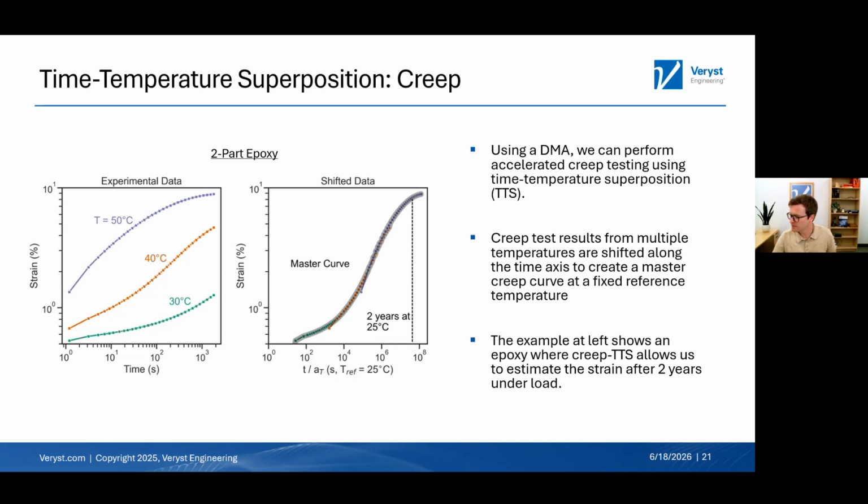How would you characterize thermal interface materials that are very compliant, to quantify stiffness in tension or compression? The short answer is that we have characterized thermal interface materials. It depends a little bit on what your actual use case is. Assuming you're talking about TIMs that are more paste-like, thermal paste materials, which are typically just inorganic particles dispersed in a polymer carrier.